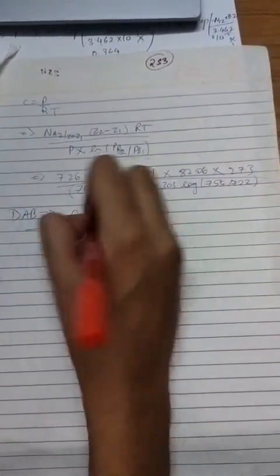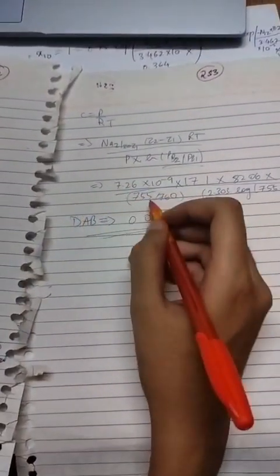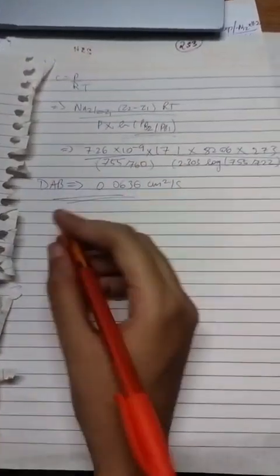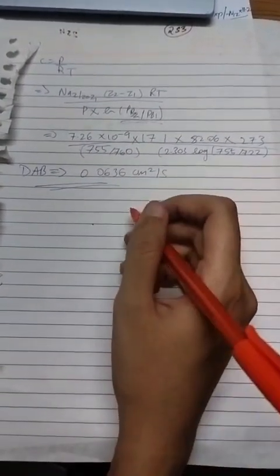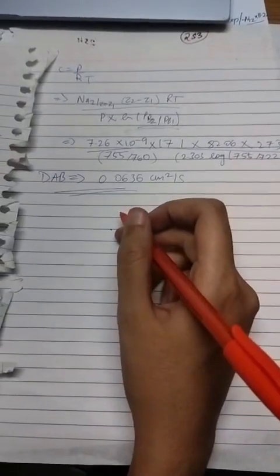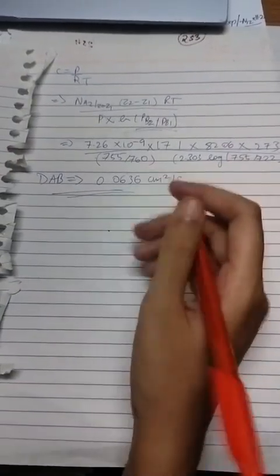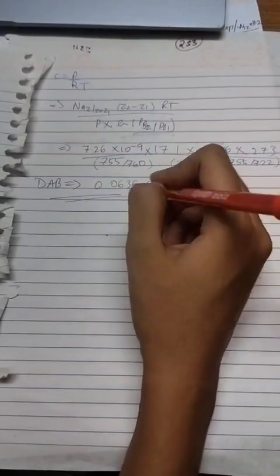This method of determining gas phase diffusivity suffers from several defects, like the cooling of the liquid by evaporation, the concentration of non-volatile impurities at the interface, the climbing of liquid up the walls of the tube, and the curvature of the meniscus. But we have assumed that all those problems are negligible here, and hence obtained our answer.